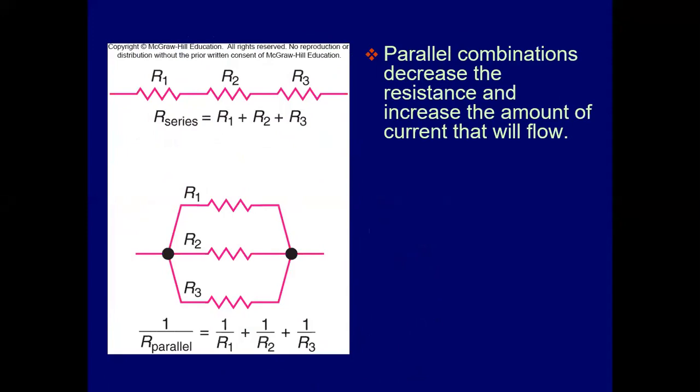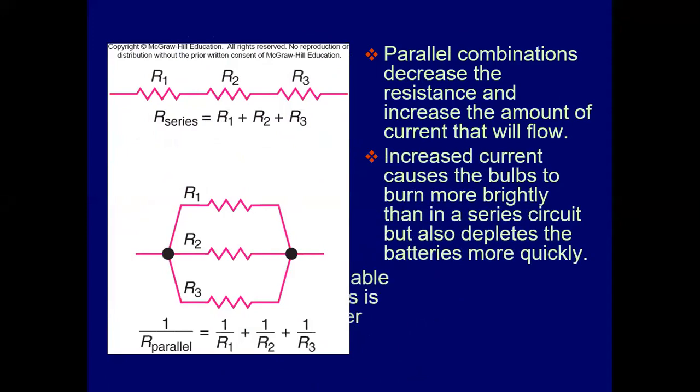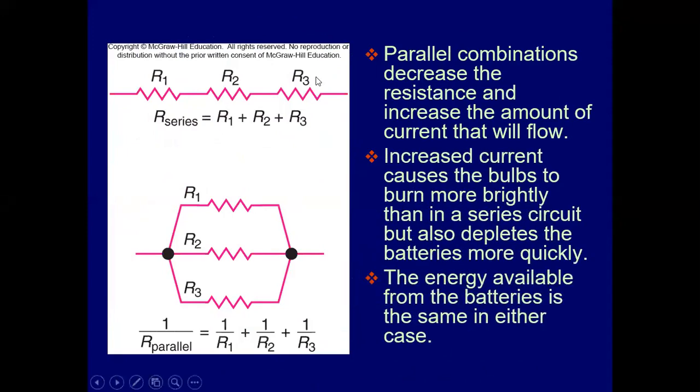All right, now here's the comparison of two circuits. So the first diagram here is a series connection of resistors. So the total resistance is the addition of three resistors. If there are more than three, you keep adding. And here's the second diagram with the parallel circuit in there. So the total resistance can be calculated using this equation.